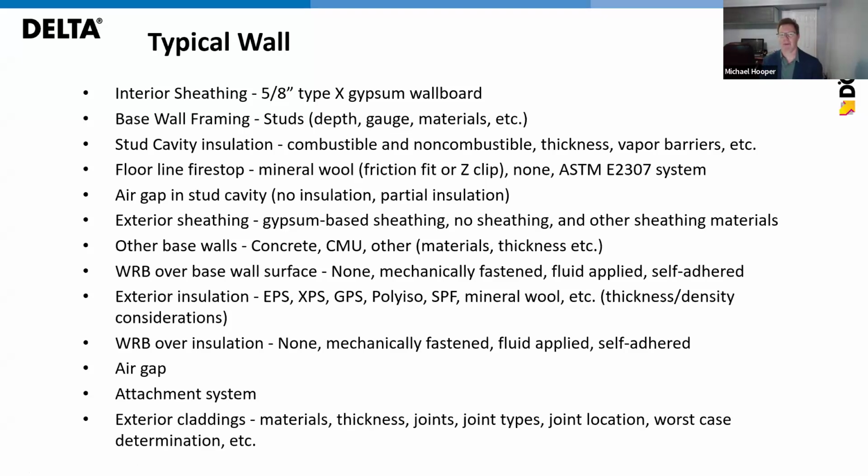You can understand that performing a scale fire test 2 stories tall can be very expensive if it has to be done many, many times. Combinations are in the tens of thousands. So we need to figure out a way to test wall assemblies and then be able to make substitutions to figure out what would be acceptable. So you kind of test to a worst case scenario, and anything that you can do to change that wall, so long as it doesn't make that wall any worse from a fire spread situation, those would be in effect grandfathered in. So let's get into that a little bit.